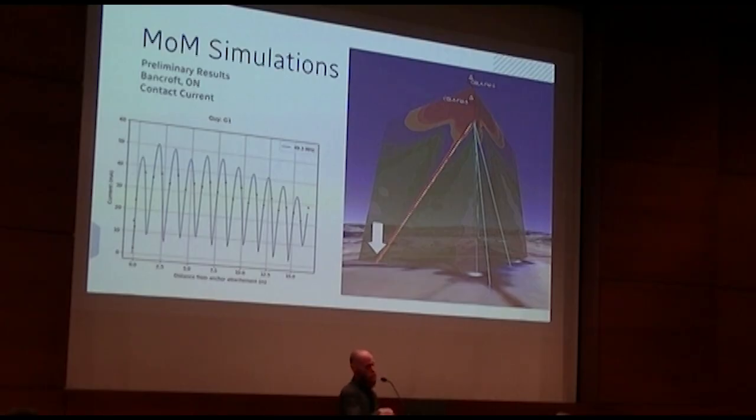The thing is that it's a near field environment, because each lump goes in the opposite direction to the next. That's the typical thing that we see in a standing wave form. So we get the current going down, being reflected at the ground and going back up. So we're going to have some standing wave there.